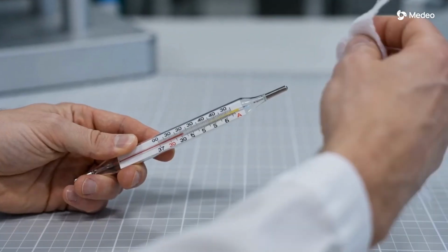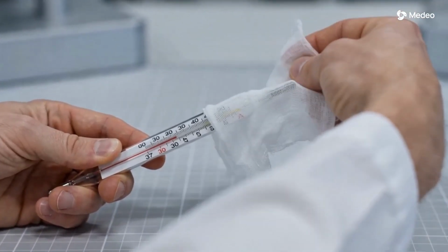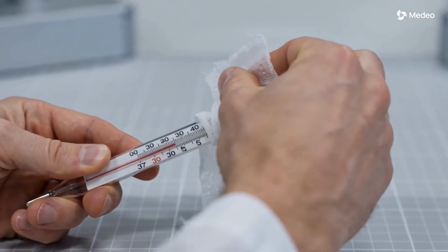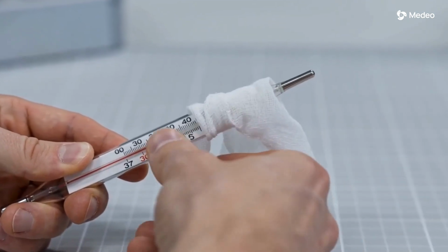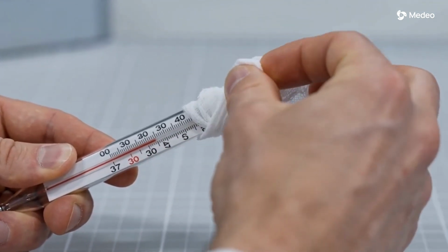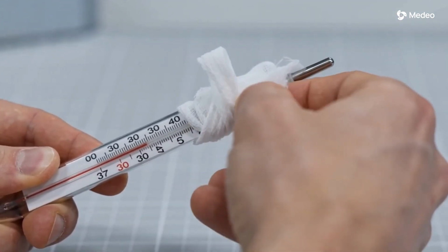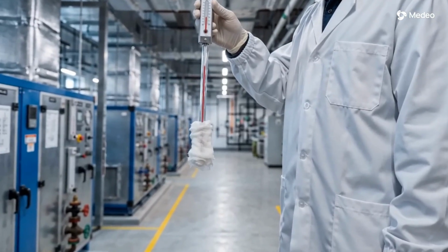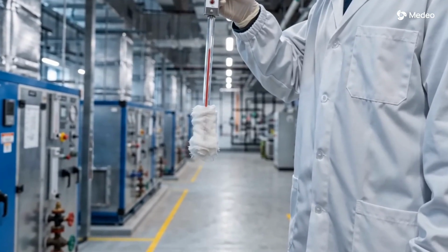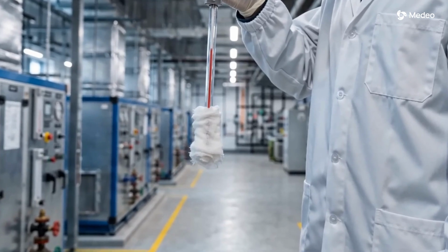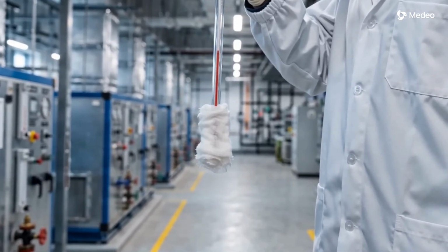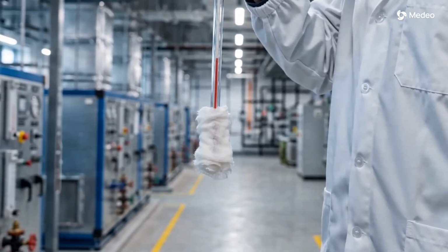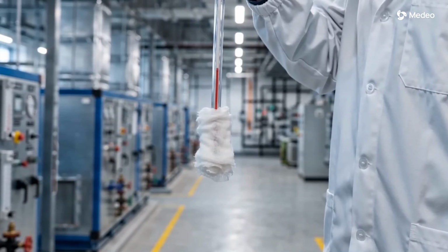Now, let's introduce the wet bulb temperature, denoted as TWB. This is measured by wrapping a thermometer in a wet cloth and allowing water to evaporate. As water evaporates, it removes heat through latent heat transfer, cooling the thermometer. The main idea is drier air means more evaporation, resulting in a lower wet bulb temperature. More humid air means less evaporation, resulting in wet bulb being close to equal to dry bulb.